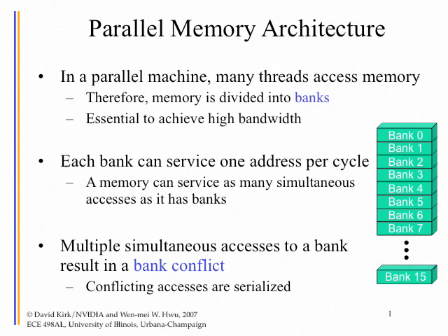If you have a very bad day and all the 8 SPs are issuing addresses that correspond to one of those 256 data elements in bank 0, then you are in bad shape, because that will take 8 cycles for bank 0 to serve. Just like if someone really just wants to talk to Foiza, 8 phone calls. Okay, you need to wait.